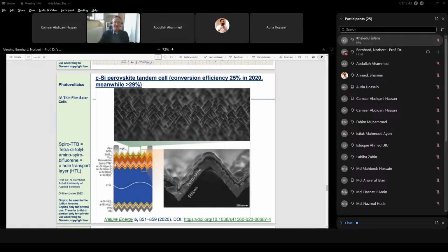The only thing I mention here, because I have this TEM picture, you see this so-called step-graded buffer layer. The sense is just to adjust the lattice constant of the germanium basis to the lattice constant of the gallium indium arsenide cell, because the cell works better the less strained the different materials are. And the lattice constants of these different materials, of course, are not 100% the same. Therefore, it helps to have such a lattice constant adjustment.